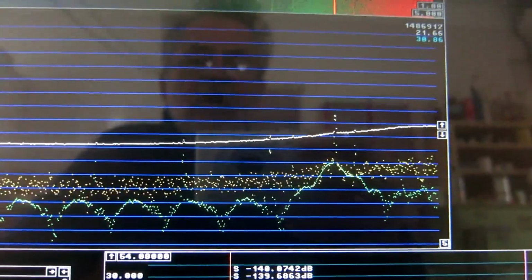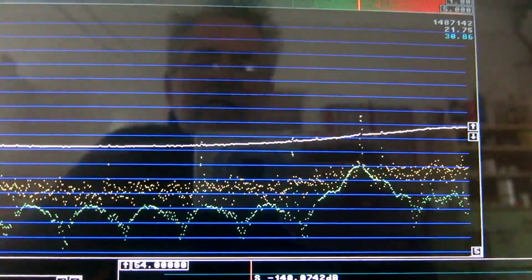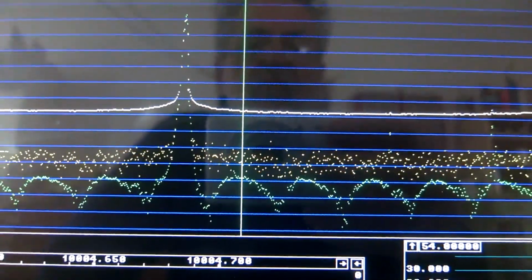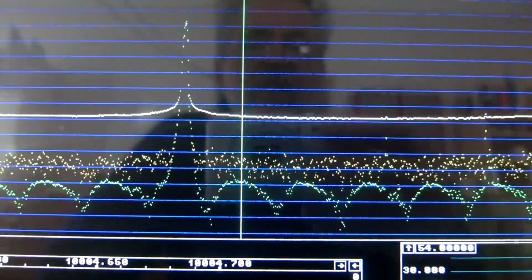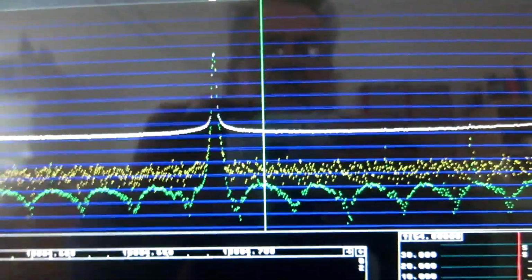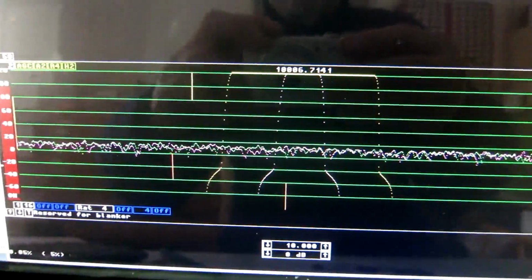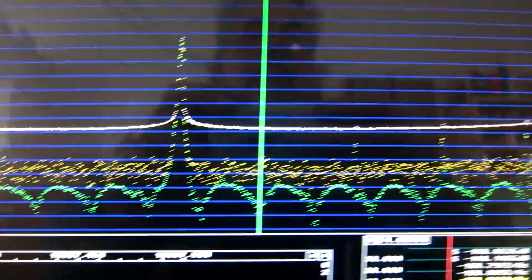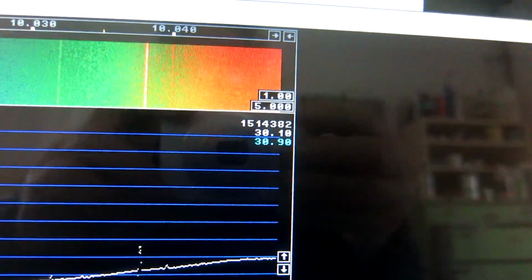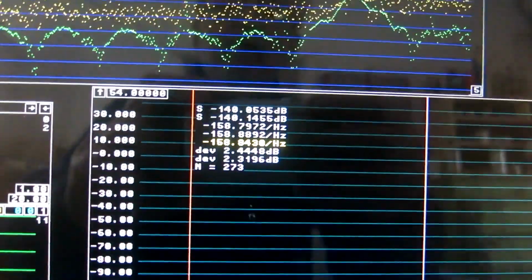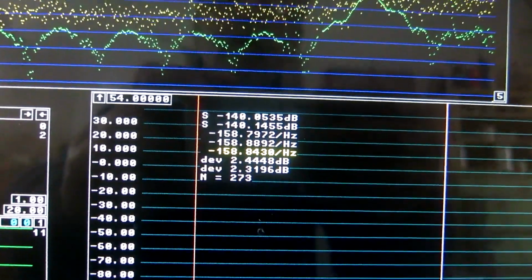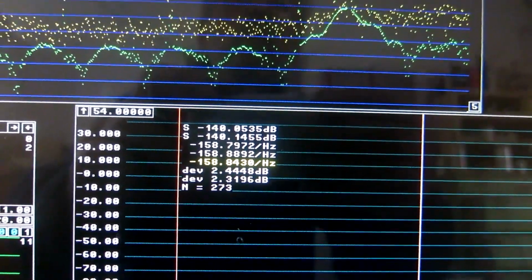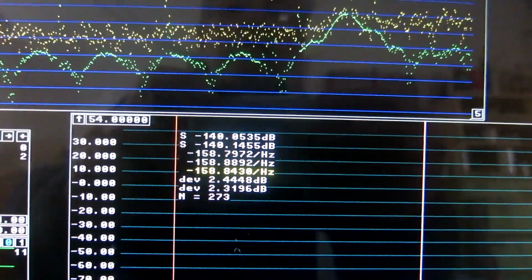That gives me about -180 dBc per Hertz as a limit for how low noise I can see. And at 6.7 kHz, here the correlation advantage is 30 dB, and here 158.8. So 159 plus 30 is 189.